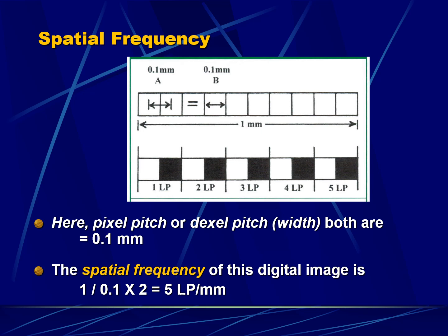And so therefore you have 5 line pairs per millimeter. Now the smallest object is a line, but we express it as line pairs, okay? Because we want contrast to affect the way we do this measure, and it will. That's why we can see the line pairs, because we can recognize the difference between bright white and black. The black one shows up because it's surrounded by white, and the white ones show up because they're surrounded by black. In other words, we have a high contrast here.